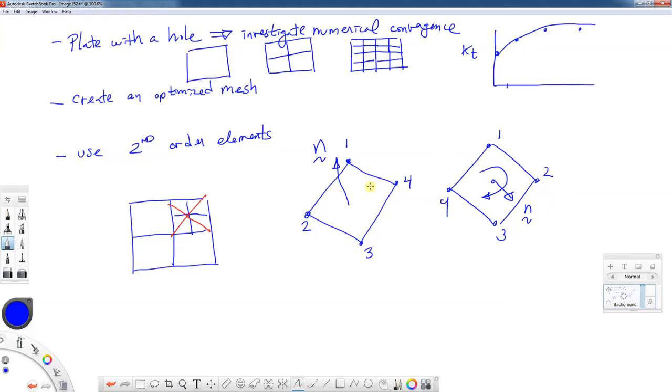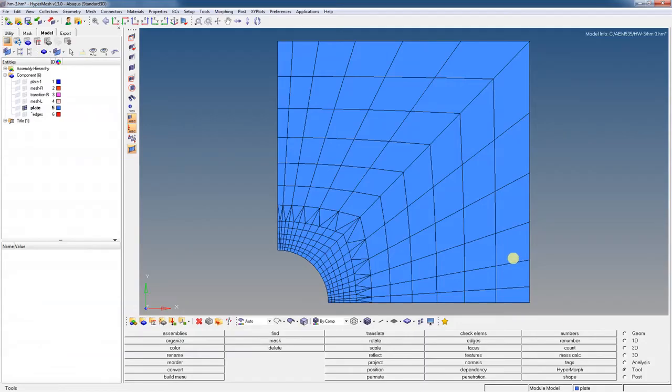If my element numbering was reversed, as I have in this second picture, 1, 2, 3, 4 that way, my right hand rule would have a unit normal that points down into the page. Okay? So the element connectivity determines the orientation of the unit normal. So as you make those triangle elements, if you consistently go 1, 2, 3 in a counterclockwise fashion, you will have the right direction for all those unit normals. It's no big deal. However, you do need to get them all straightened out before you export the mesh. So that's where we're at now. We're getting ready to export the mesh.